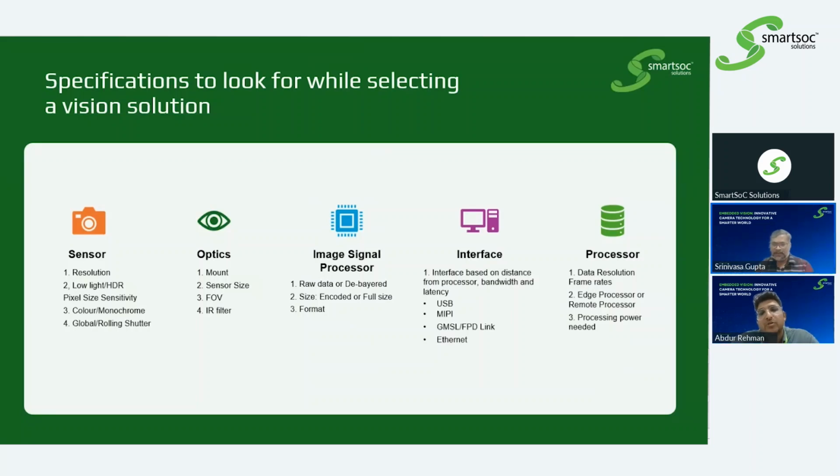Understood. So there are different sensors like CMOS and CCD and others. CMOS is the fastest one, but for some applications like space, CCD is better. Quality is very important there, and sensitivity is very high. But for all other applications, the CMOS image sensor is the correct one, where we get accuracy, quality, and even speed. So that's how CMOS image sensor is better.